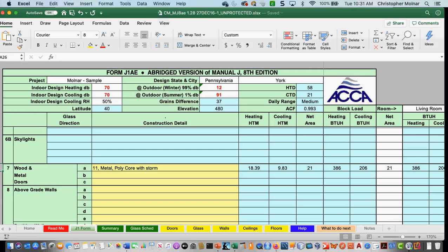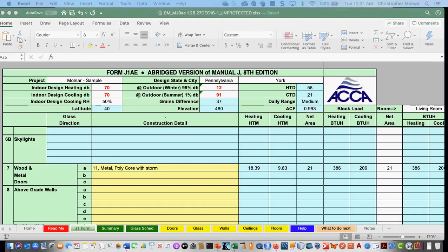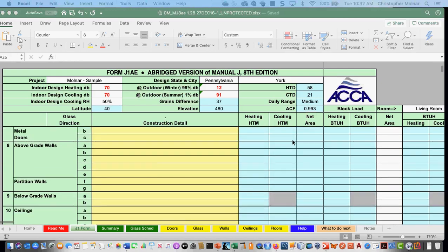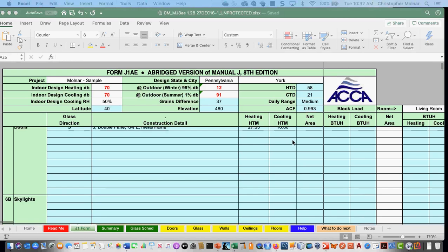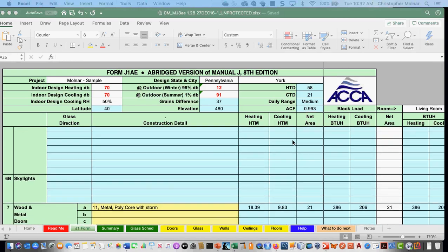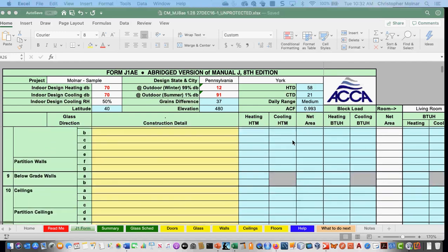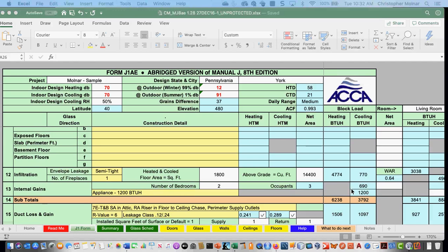Real quick, if I'm doing the bedroom with my office, is there anything in this program, because I'm going to end up putting it under the office, or do I have to have it under the name bedroom? For the occupants? Just the total occupants, wherever you put them. So I can put it under office. Yeah, room name I couldn't care less about. Neither could the program. It will not let you go forward if the total occupants don't match, because of the ventilation requirements in each space.